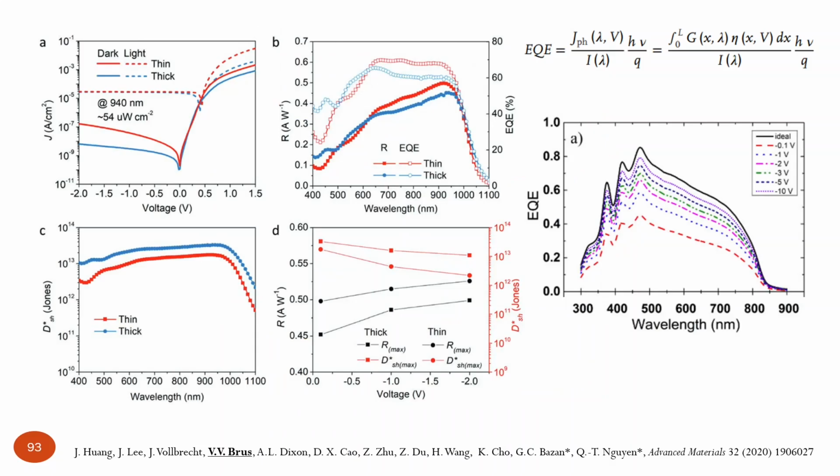So now let us focus on photodiode main characteristics. Obviously that is the current voltage characteristic, so this first figure A. We care for photodiodes specifically in this part for reverse bias, because they should operate at reverse bias. So we want to know what is the dark current for this photodiode at reverse bias.